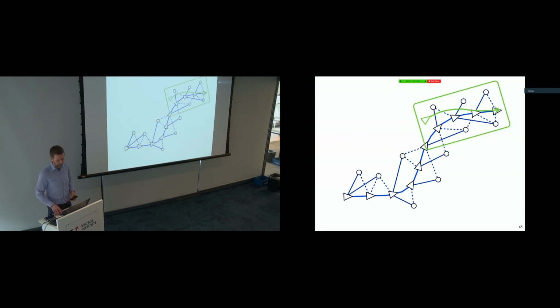Once we know where we are, we can, of course, do another rubber band for control. So we can run something like model predictive control, where we look at the shape of the path ahead and try to figure out exactly what commands to apply to the vehicle, to get it back onto the path if it's a little bit off. And so basically the lesson for all of this is that a lot of robot navigation is really just a local decision-making process. We don't really need global information if all we're trying to do is something like track a path.